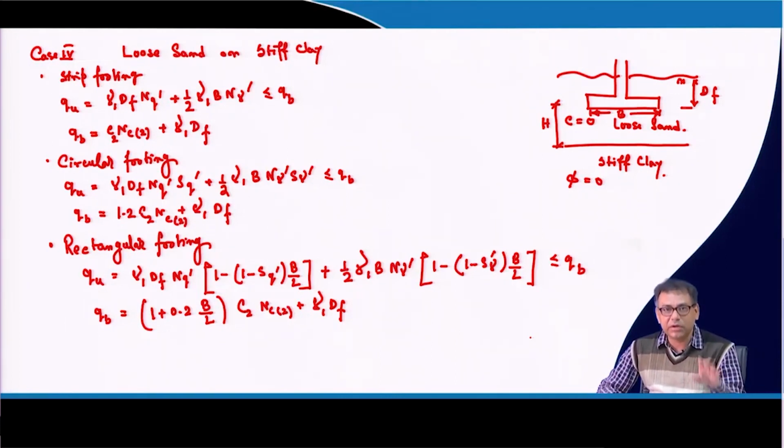If you have those data, you put those corrections here and then you incorporate the soil compressibility effect also, because that is important. Not all soils are stronger soils, some are weaker soils also. But these recommendations are not given in the original theory. So you have to collect those data and check whether some soil compressibility effect is there, or whether you have to put those corrections.